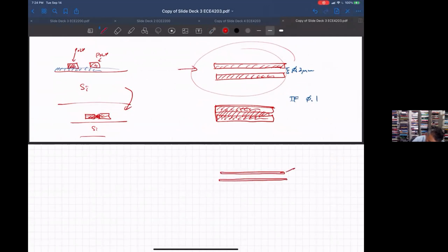Let's say they tell you, if you make something that's less than 0.1 micron, I'm just making up these numbers, you think you've drawn two really narrow polysilicon lines, but in fact, when I do my etch process or my lithography process, at some points you might get an opening in these lines. I can't resolve these lines. I might get God knows what.